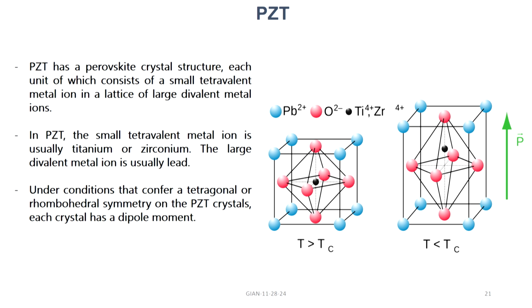But once you go below the Curie temperature, there is a slight displacement of the central ion, and so the centers of positive and negative charges do not overlap any longer. So, there is a net accumulation of positive and negative charges separated by a small distance. So, there is net polarization, and this small polarization is the one that is responsible for the spontaneous polarization and the ferroelectric order. This is true for barium titanate as well.